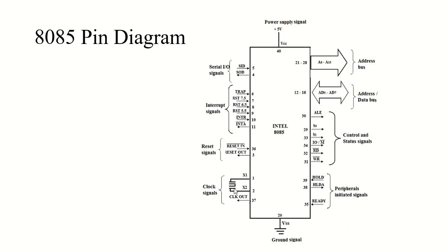Then the auxiliary carry flag, which will be set whenever there has been a carry out of the low nibble into the high nibble, or a borrow from the high nibble into the low nibble of an 8-bit quantity, so the low order byte of a 16-bit quantity. Except that, the auxiliary carry will remain reset. And this flag will be used by the decimal arithmetic instruction.